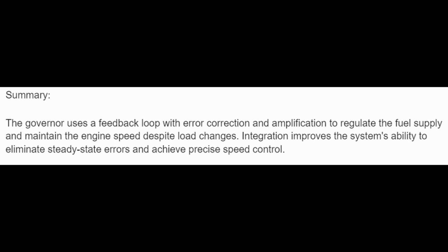In summary, the governor uses a feedback loop with error correction and amplification to regulate the fuel supply and maintain the engine speed despite load changes. Integration improves the system's ability to eliminate steady-state errors and achieve precise speed control.